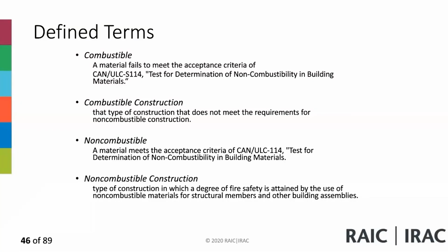What are non-combustible materials? They include brick, ceramic tile, concrete made from Portland cement with non-combustible aggregates. So you've got to be careful with those new concretes and with the additives that they have in them. If they have all these new additives and you don't know what they are and what their performance is, you've got to ask about it.